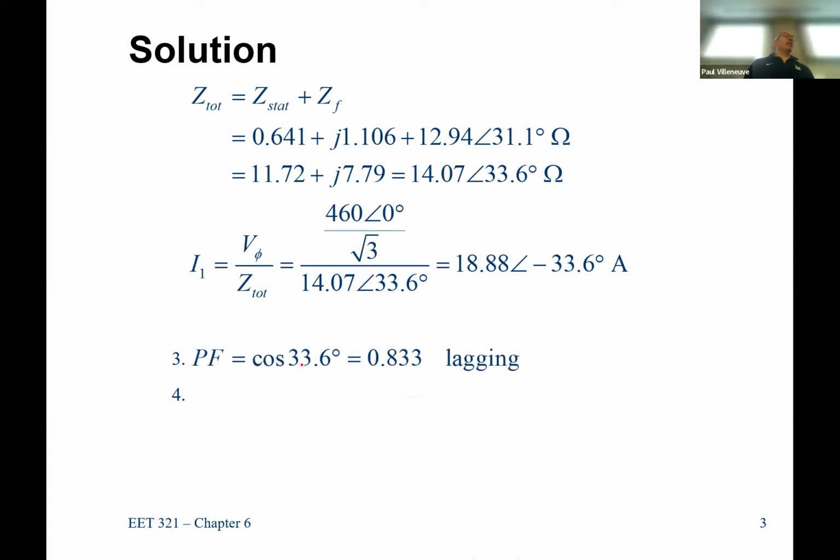Why do we calculate the angle? Because most of us as electrical engineers are only really interested in what cable size do I need. So I've got to run a 460 volt, 25 horsepower motor that's going to be operated at slip. Then it's going to be pulling around 19 amps. So I can probably get by with a number 12 conductor to go ahead and feed that, because a number 12 conductor is good for 20 amps.